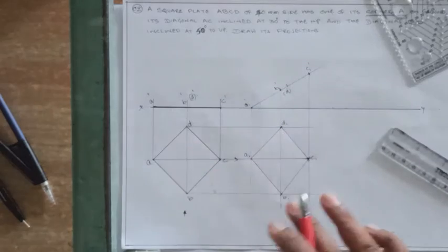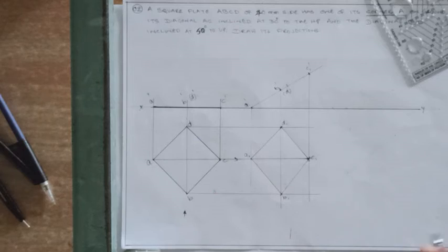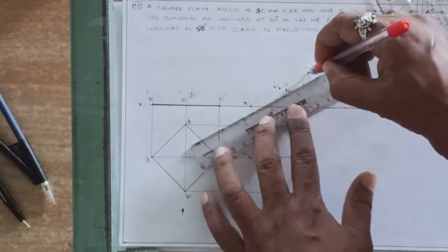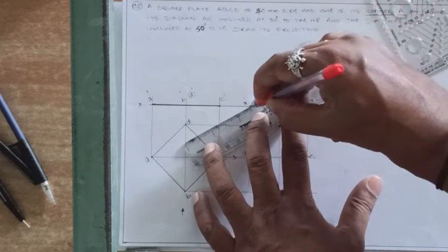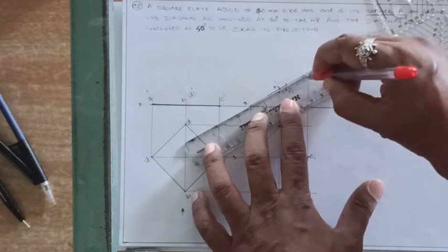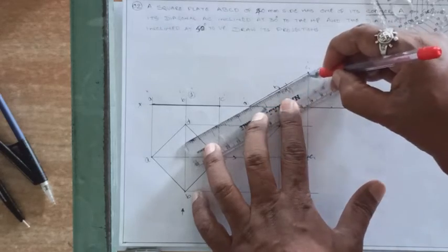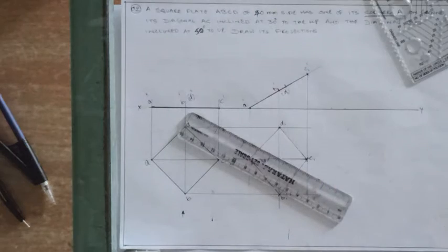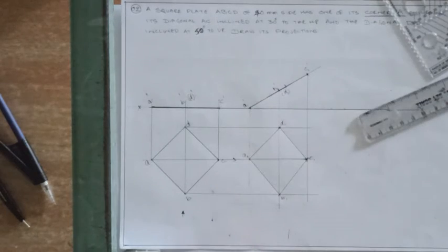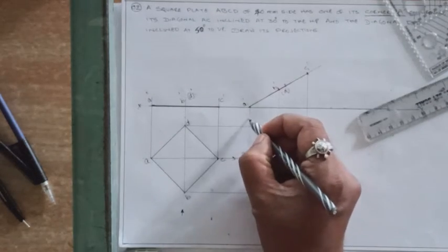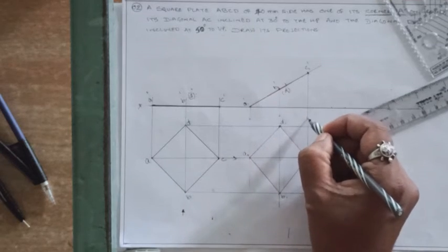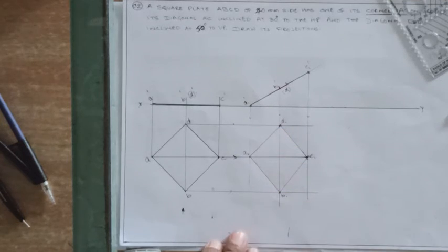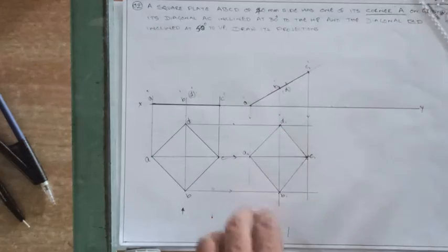So here also we will get a square similar to this, but of shortened length, and you can make a thick line in the front view between A1 dash and C1 dash, a little thick line, because these two views are required views, right? Now, if you want, you can mark the arrow marks, not necessary, already you know how to draw the projections and from which direction and all these things, now you know it.